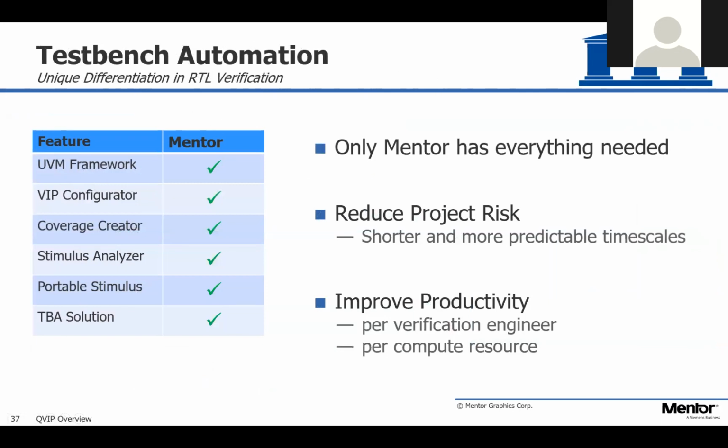That is the one thing, that all of these verification IP components are UVM agents. So you do need to have a UVM test bench. Mentor provides the UVM framework to help you get started creating a UVM test bench. The VIP configurator will help you configure those verification components for whatever your need is, and to integrate them back with the UVM framework. It creates coverage so that you can say what kind of coverage you are interested in, what features you want to test. And it will collect all the coverage to make sure you've done that.